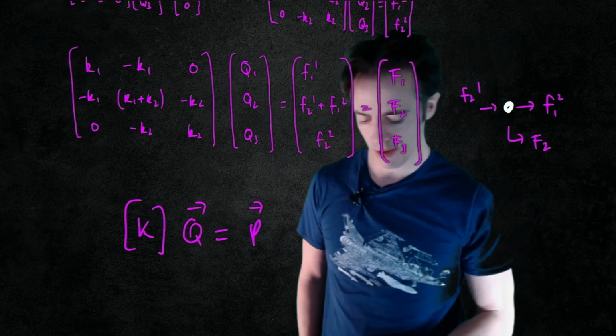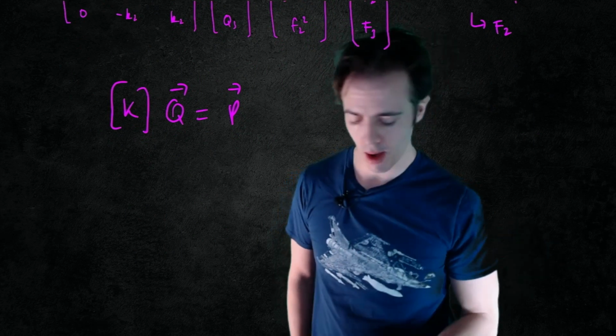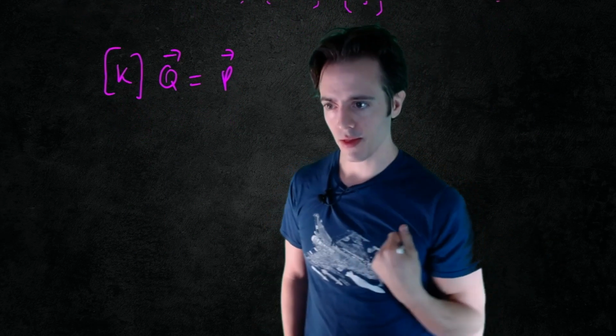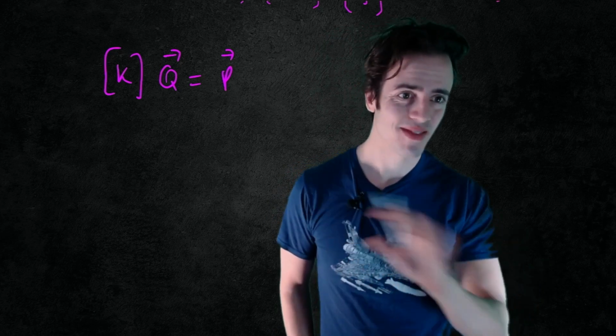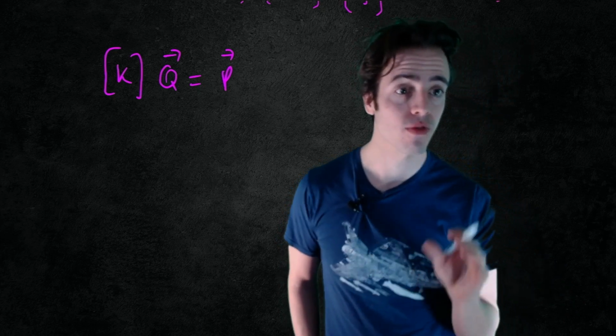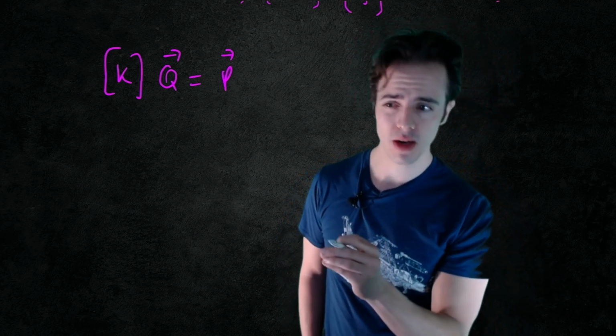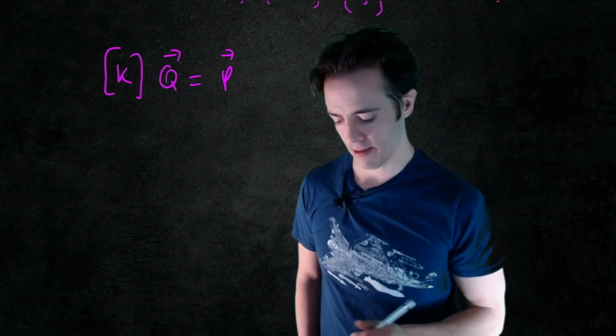And we set this up for this problem, and we then went ahead and solved it. I've just noticed a mistake in the notes. It's very minor. I said in the notes that K1 and K2 had values of 50 and 75 pascals. That's the wrong units. Stiffness has units of newtons per meter. So I could have put Pascal meters, but I was wrong. It should be newtons per meter.